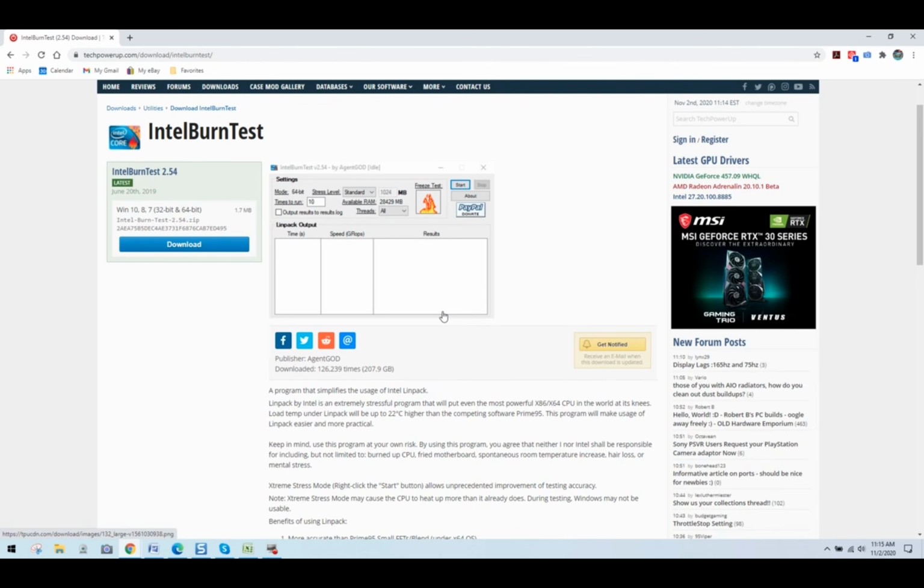The other factor many of you seem to ignore, and I've seen this numerous times, and I don't know why, is that you don't take into account temperature. Ambient temperature of where your system is going to play a tremendous role on how stable it is. If you go into a commercial CNC facility, you're not going to find that there's no air conditioning, that these systems are just, grease all over them, they're sloppy. You've got a $250,000 Haas machine, it's going to be golden, because usually the business owner / programmer / end user will realize exactly what investment that company has, and they want to make sure that machine is pristine, as I would hope many of you would.